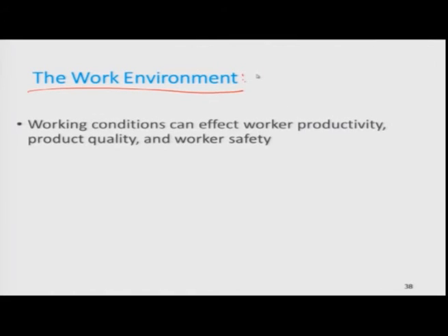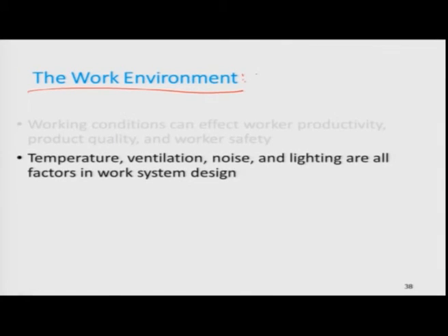Now, I will explain the work environment. After chart preparation and job designing, now we will come to work environment. This is also a very important factor. Okay. Here working conditions can affect worker productivity, product quality and worker safety. Temperature, ventilation, noise and lighting are all factors in work system design.